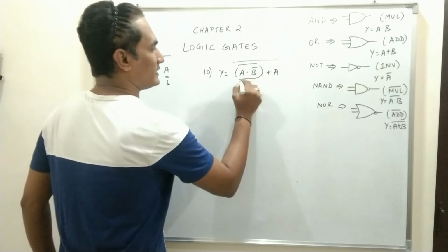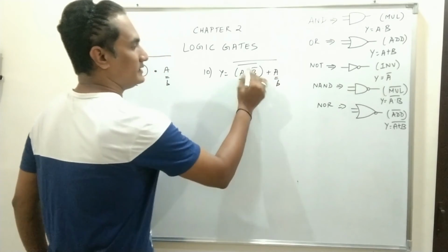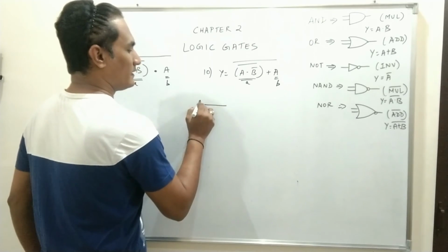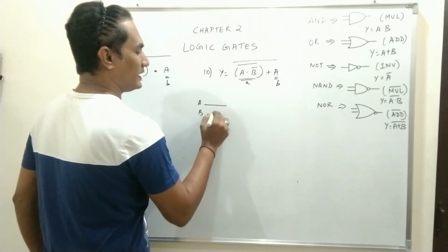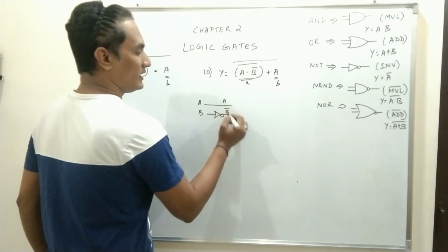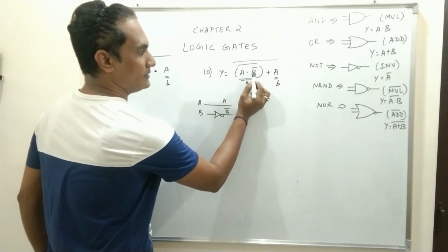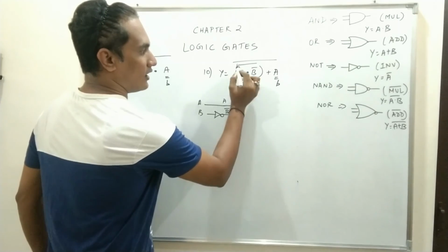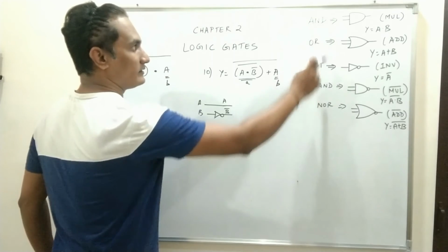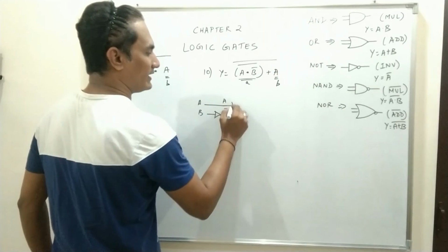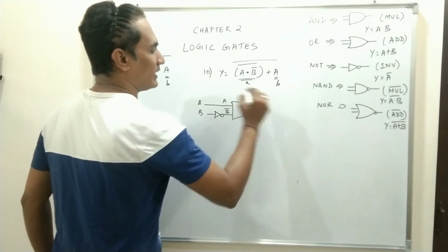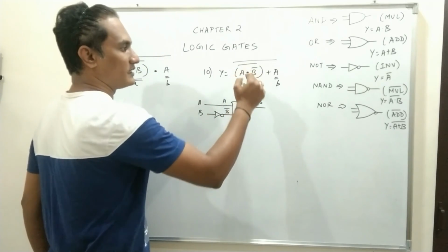So first you take this as expression A, this is B, take this one, so it will be A and B connected by a NOT gate, which will give you B bar. So this is A and B bar. A and B bar is connected by dot over bar sign, and dot means AND gate, bar sign over it is complement of AND, which is NAND gate. So this will be A dot B bar whole bar. So you got expression A.